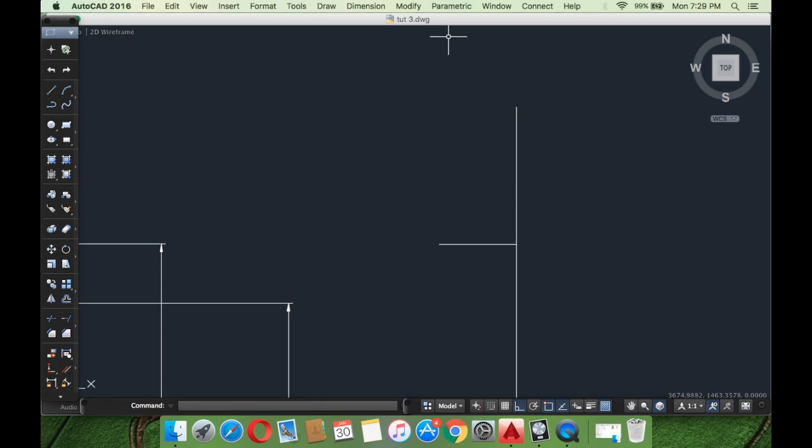It's as simple as that. I specify the boundary and then I get to cut the object. I repeat the whole thing. So I have the trim command again from the toolbar. I select the boundary, suppose this one, press enter, then click on over here. There we have it. It's as easy as that.